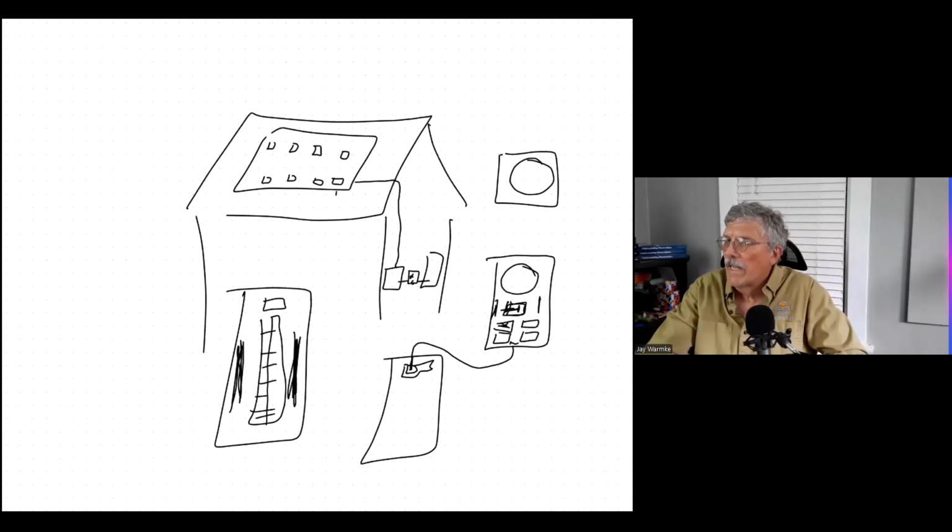So you'd have to get an electrician to come in, or do it yourself, I guess, if you're good at that. Turn this off and then separate out all of those wires. So all the white wires are going to one bus bar, all the copper wires are going to another. And if there is a bonding jumper, often in one of the bus bars there's going to be a green screw, and that green screw goes down and connects this to the case, and that's how these two are bonded together.